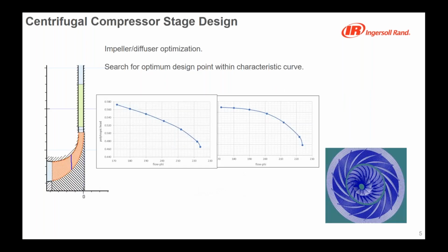So let's start looking into one of the challenges that we can face while designing a new centrifugal compressor. We can have a very simple case, that's the stage design. Here I have indicated a really simple example that is one of the components. It's just the design of an impeller and a diffuser with the characterization of the polytropic curves, so polytropic head and polytropic efficiency.